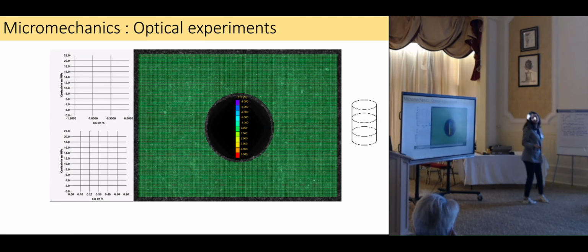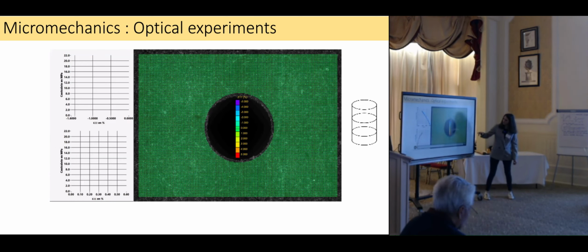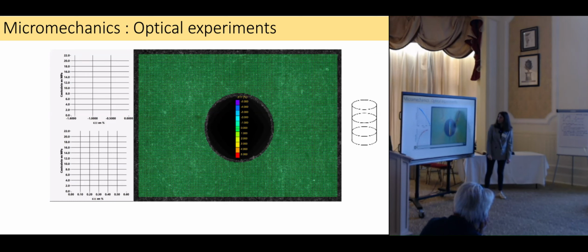So the pictures are taken quite quickly, so that we have time to see the propagation and what is going on. So what you see is that at the beginning, you have what you expected to happen, so fracture propagating at the tip of your stress concentrator. But actually, the final mechanism for failure is not going to be just a simple mode 1 crack opening here.